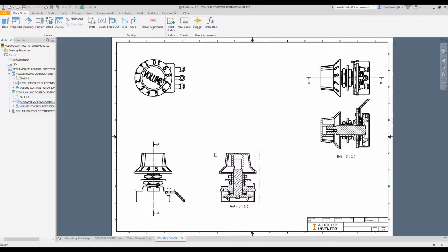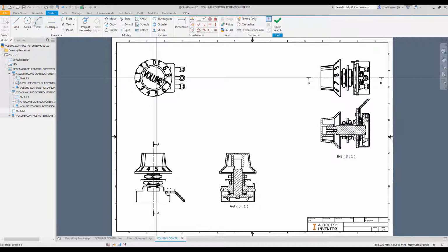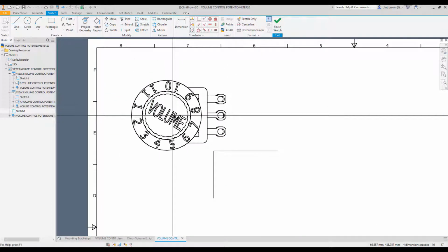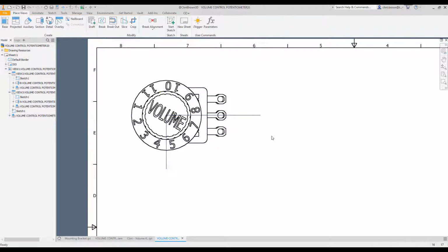Our second option is actually to use a view sketch. So you'll see we have view sketch over here, and if I click on that, choose the view I want to draw on, I can now put in precise lines. So if I start out by drawing them over here, I can now use projected geometry. So maybe we want to grab the midpoint over there, and I can make the midpoint of my new section line coincident with the midpoint. And as before, I can add in dimensions to set the size of these lines. And then I can finish my sketch.